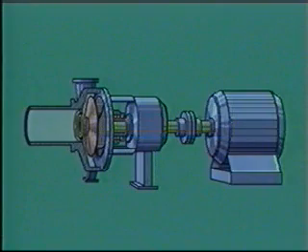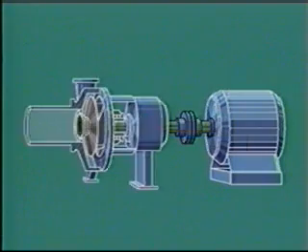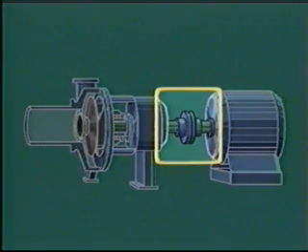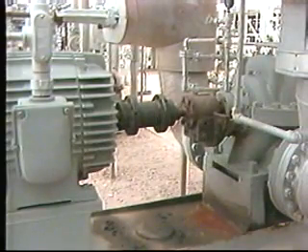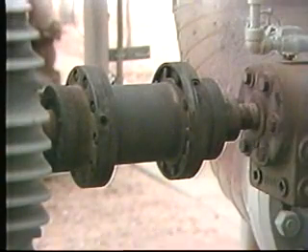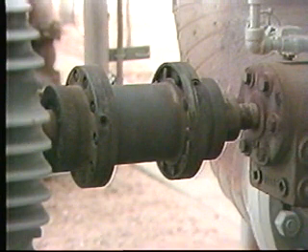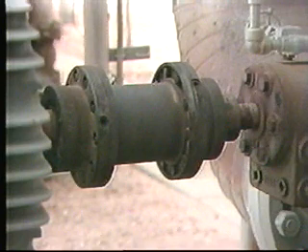Let's stop. Here's the driver. There's the pump itself. What links them? This, the coupling. It connects or couples the driver to the pump, and it does so for a purpose: to transmit power from the drive shaft to the pump shaft. Although they might seem simple, couplings are as critical as all the other components. They've got to be strong enough to withstand sudden changes in the pump's load and also those times when the driver might stop.